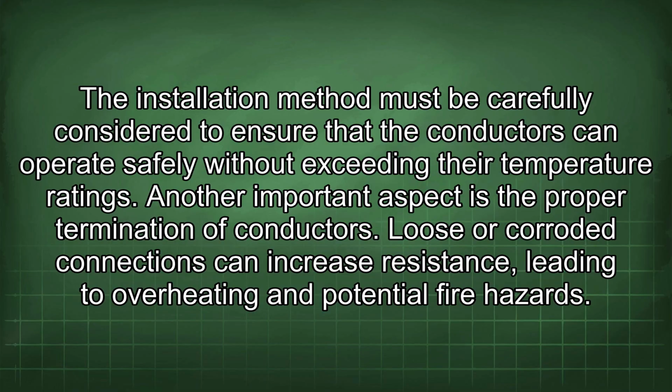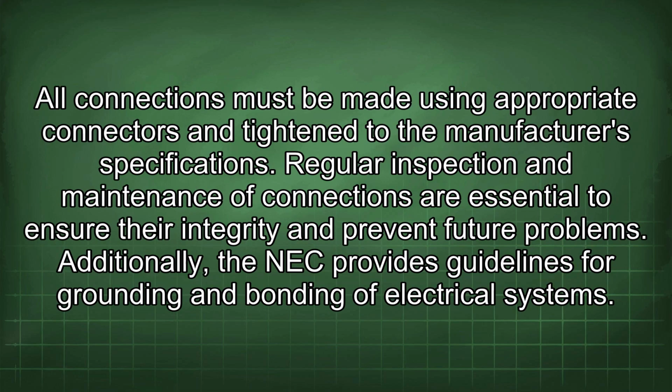Another important aspect is the proper termination of conductors. Loose or corroded connections can increase resistance, leading to overheating and potential fire hazards. All connections must be made using appropriate connectors and tightened to the manufacturer's specifications. Regular inspection and maintenance of connections are essential to ensure their integrity and prevent future problems.